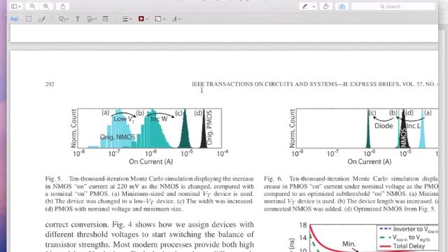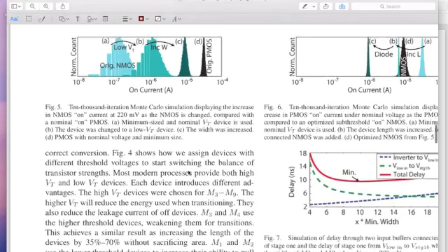And we want to swap these two, right? We want to make the NMOS stronger than the PMOS. So what they do is, by changing this from low VT to high VT, everything is high VT, but just the NMOSes they change to low VT. It does help push up the drive current, but it's not sufficient to cross. In addition, what they do is they increase the sizing. How do they increase the sizing?